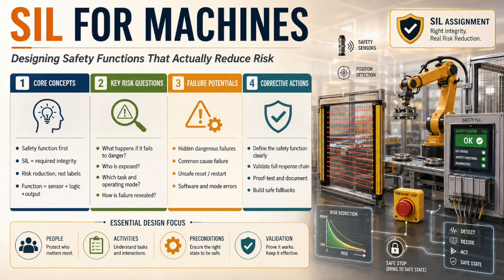Blind reset is dangerous. Remote restart is dangerous. Automatic restart after power recovery is dangerous. Restart after fault clearance without awareness is dangerous. Many severe accidents happen not when the machine first fails, but when it unexpectedly comes back to life.